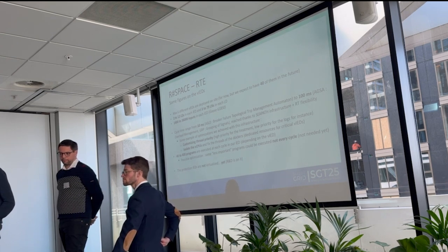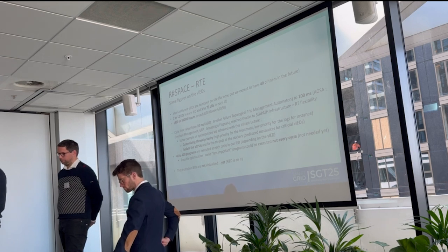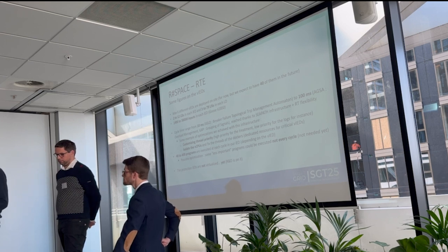And the only problem that you would have dealing with SR-IOV would be that in some cases you also need network redundancy using, for example, HSR or PRP. And today we didn't find any network card capable of doing SR-IOV and PRP. So you have to choose which one you want. Okay. Thank you.